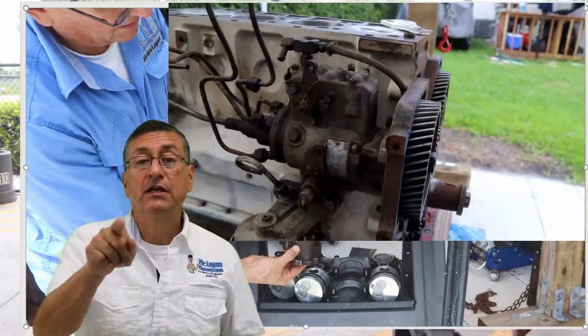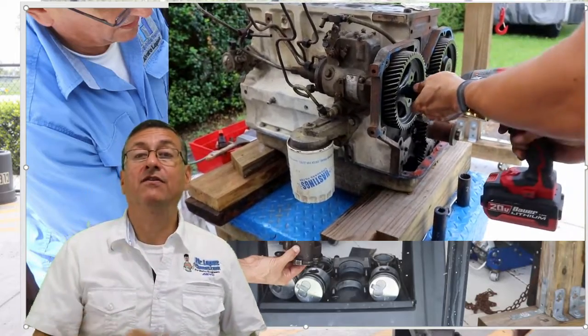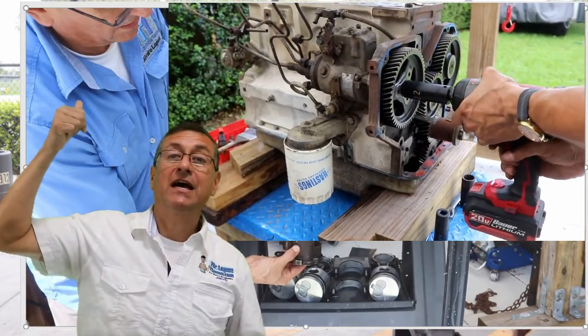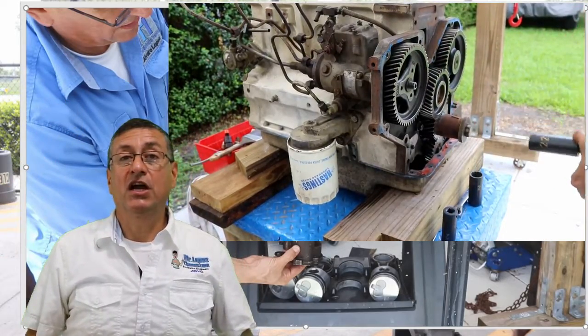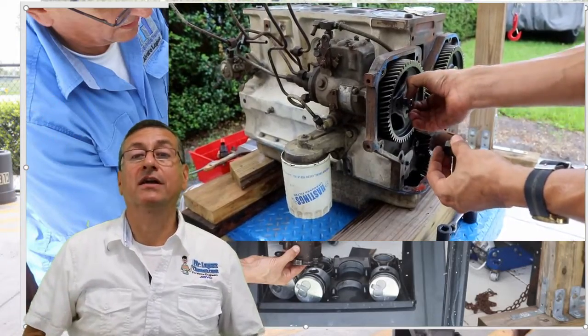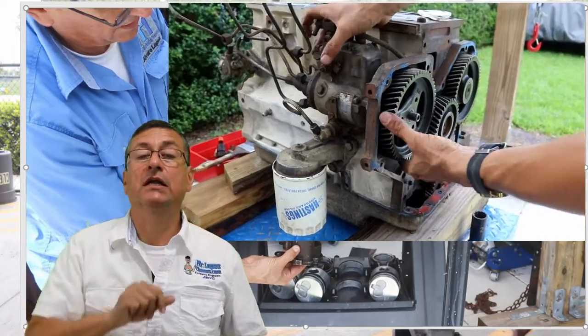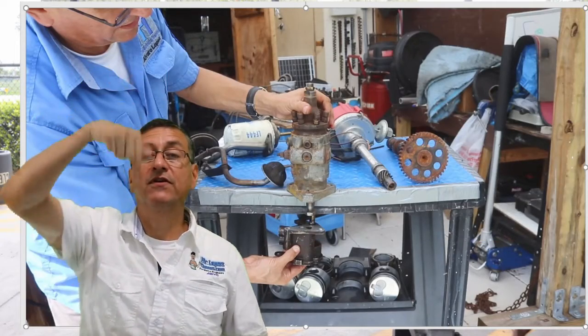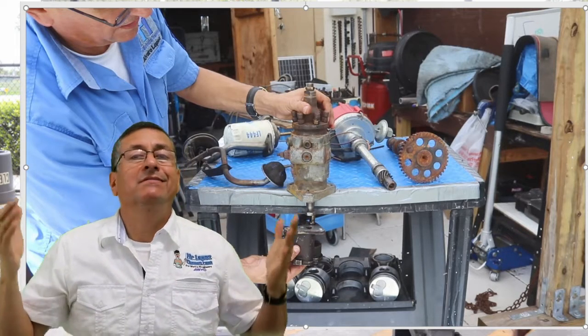In this particular case, this fuel injection pump is vertical and engaged with the shaft of the oil pump. In some cases, the fuel injection pump is horizontal, and the gear of the crankshaft engages with the gear of the camshaft and with the gear of the fuel injection pump. Those three gears work together when the pump is mounted horizontally.